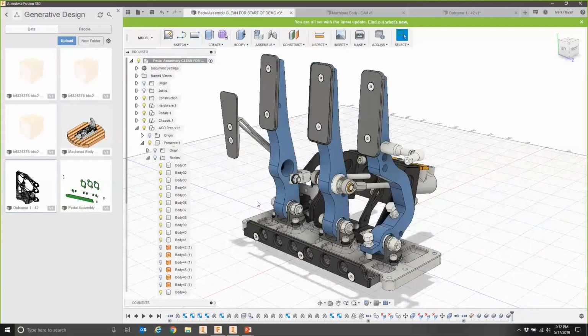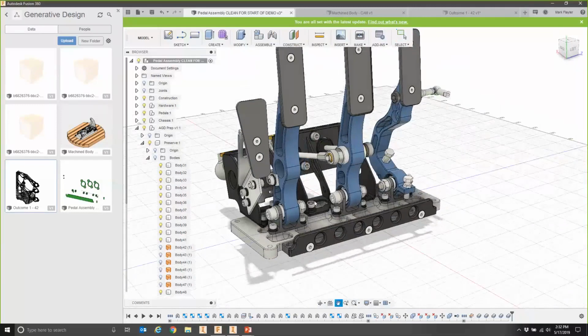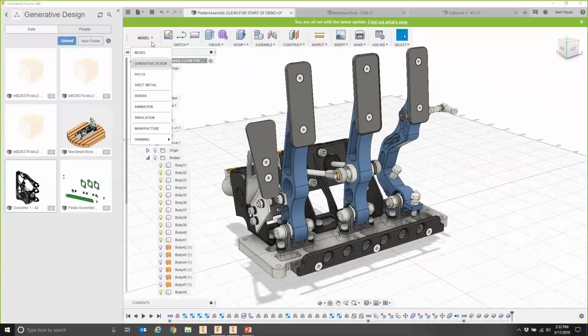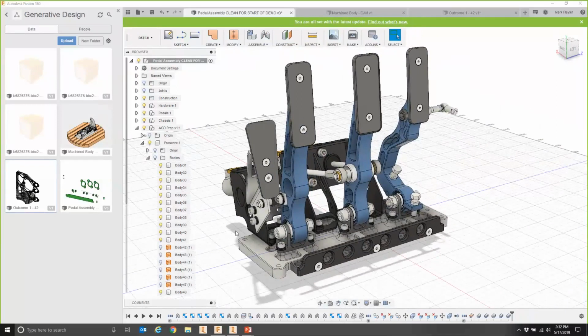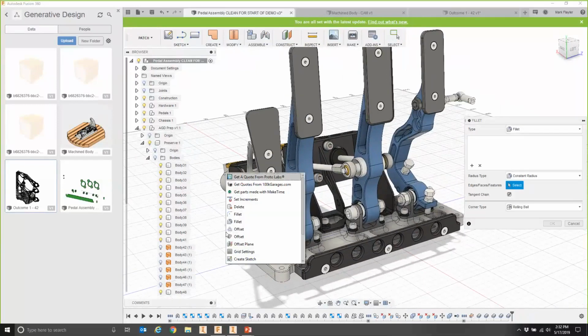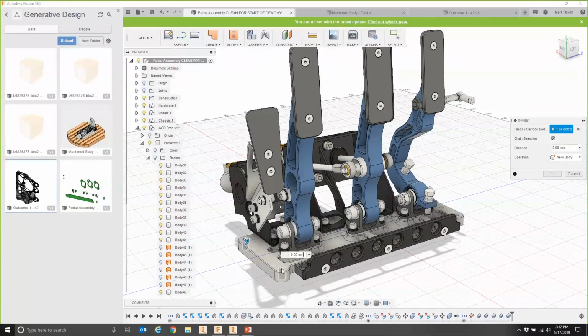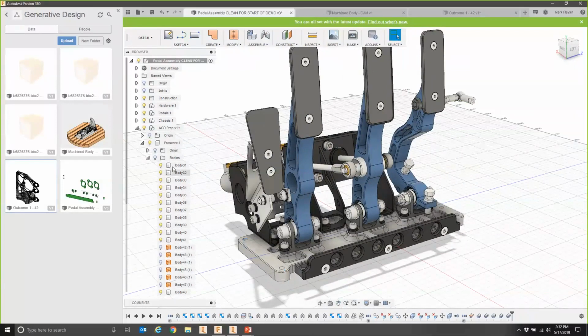Now, the way we go about this inside of Fusion is very similar to how we would do it inside of Inventor. You have an environment here called a patch environment, and this is typically where you can come in and create some offset surfaces, which you can then create as solids that you might use for preserving regions, okay? And some of this has already been done.